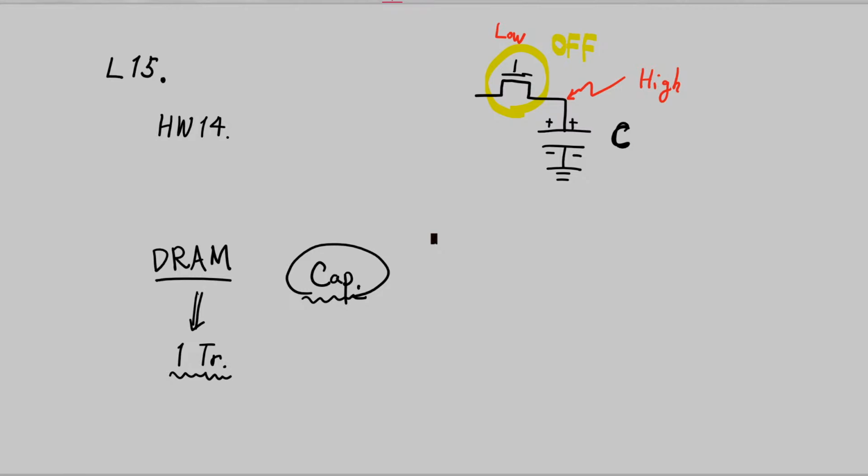However, unfortunately, we know that there is a certain amount of current due to our leakage mechanism. So yes, the stored data is just leaked by this leakage mechanism. So if we observe, for example, stored charge as a function of time, and this is time 0, after that we will have a reduced number of charges stored in our capacitor.